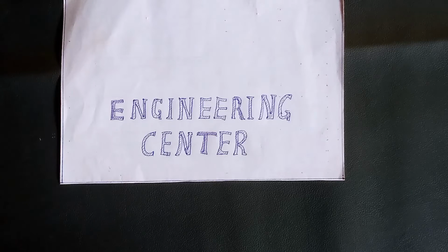In today's video, we are going to go through 6 rules used in block reduction. At times you may be told to reduce a certain block diagram to canonical form, and then you can be told to get the ratios. For example, you can be told to get the transfer function, that is the C/R ratio. Now, what I mean by a canonical block diagram is a diagram with one feedback element and one input. Consider the rules that follow.